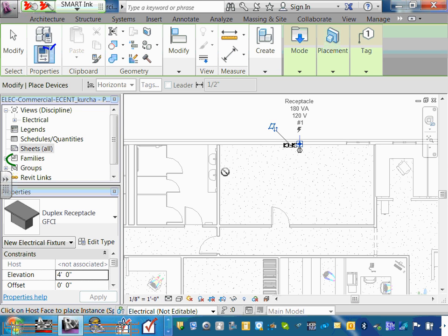That's how Revit works. The family is looking for a host. So I can't drop this receptacle in the floor because this particular one is not meant to be in the floor. It has to be in the wall, unless you put it in a door if you want. Oh, or a door. A host is a door, yeah.